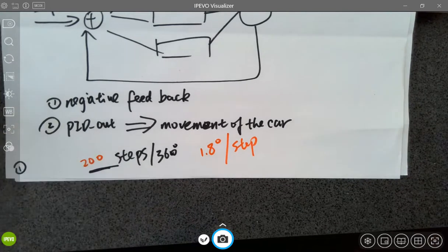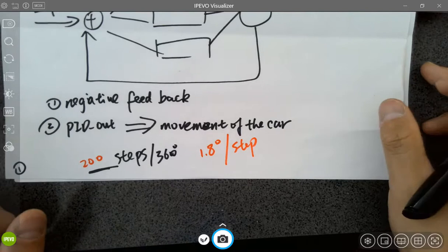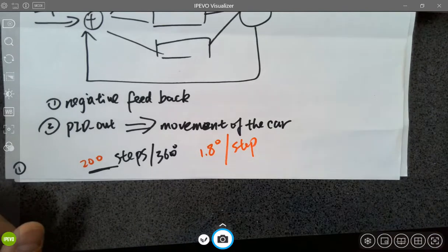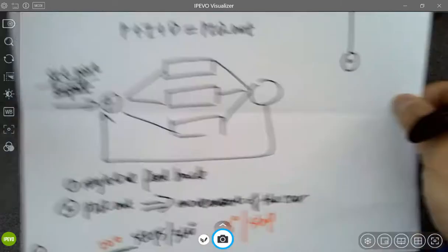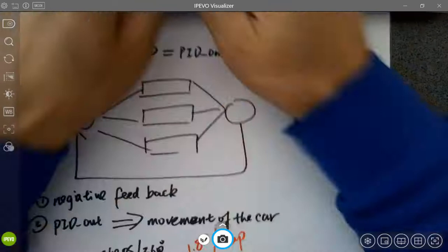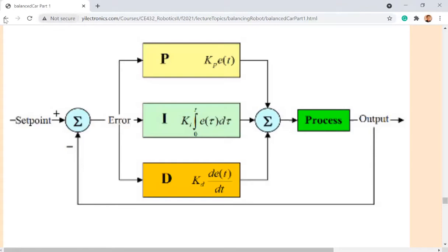So a bigger angle, we want to run a different number of steps. A bigger angle, then more steps, right? That's the reason I want to use a stepper motor, because they are accurate. Every step is exactly 1.8 degrees. Now let's see, it's kind of tricky. How do we convert it in there? The algorithm from the original author used time delays instead of directly converting it into number of steps. We'll think about why he has to do that. We have to look at the code first so you know what I'm talking about, okay?